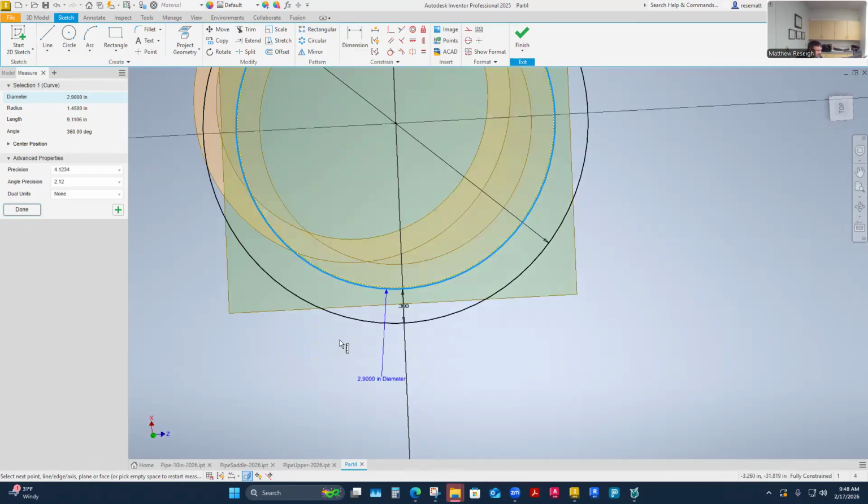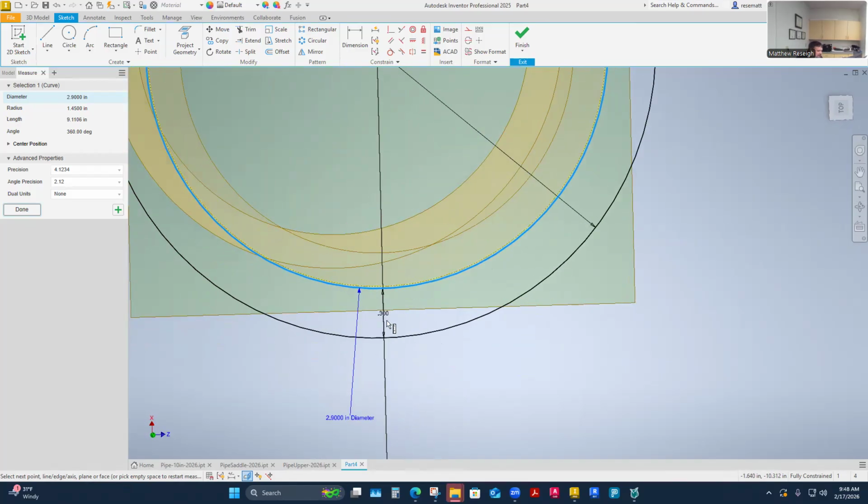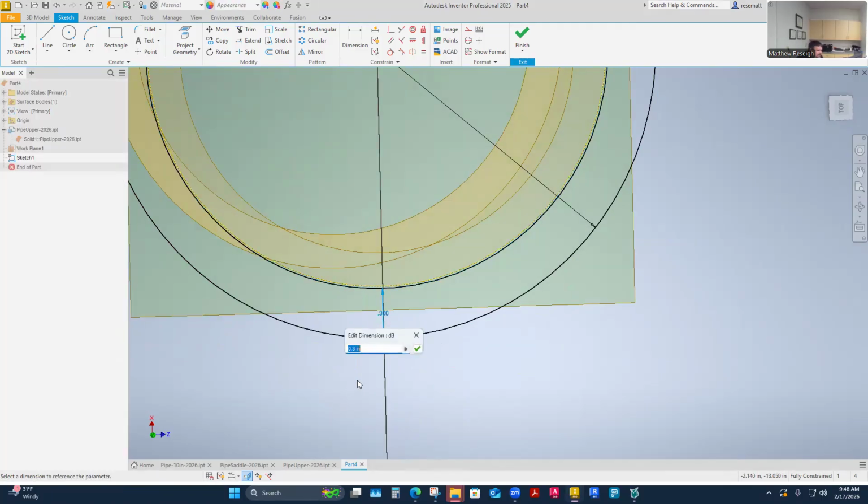So I think this is just going to be a little bit tight. I like it, it's clearance. But I think I'm going to go for the sloppy fit, and it's just based off me knowing that my pipe stand is probably not super critical. An 1/8 inch or a 0.09 gap all the way around. I'm thinking I can weld that. It's almost like a good root opening. It might make me have to take two passes around that, like one root and then one fill. And that could slow us down a little bit.